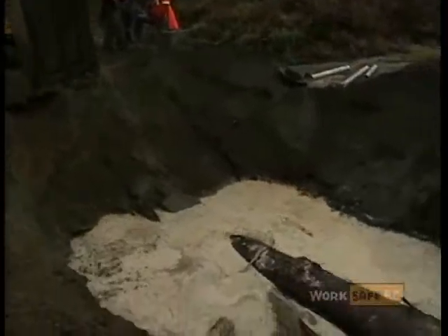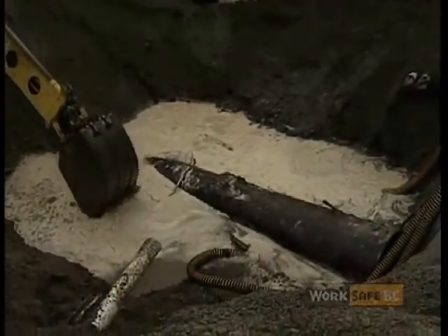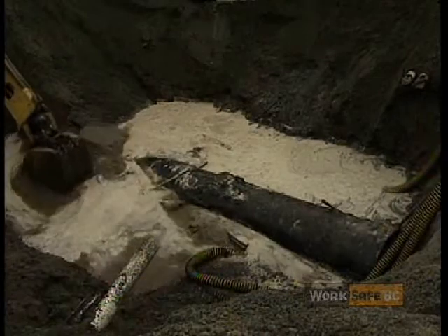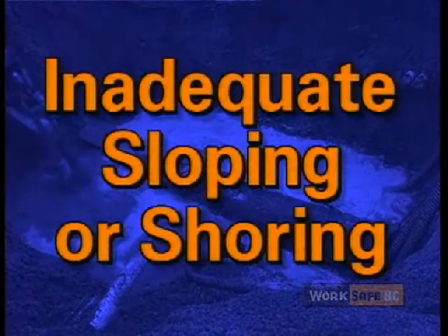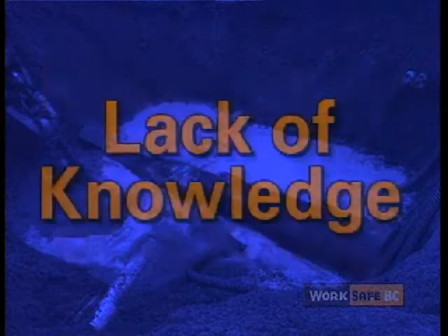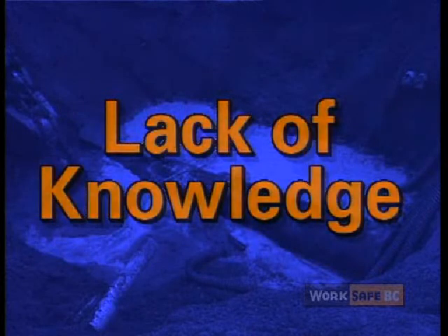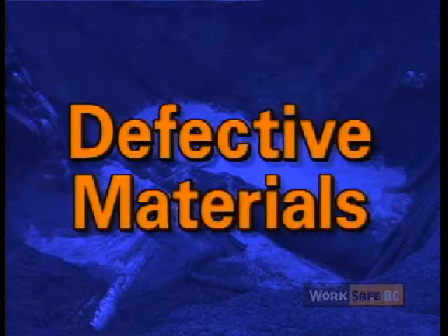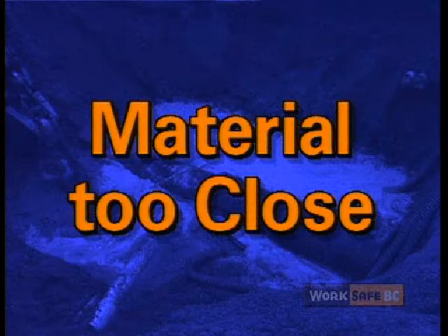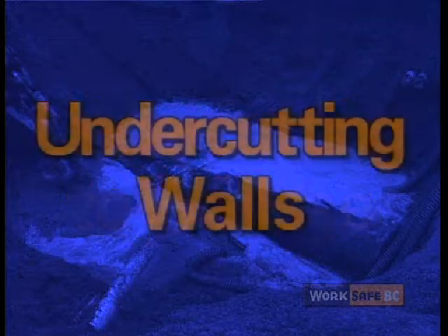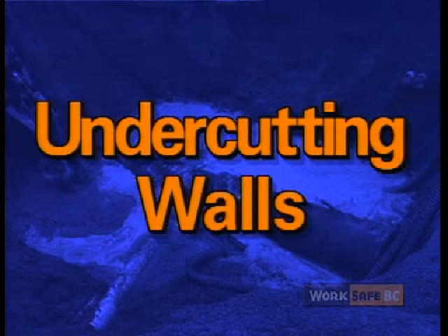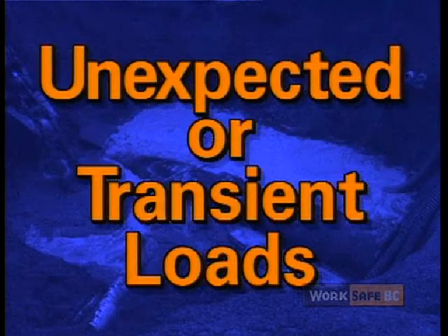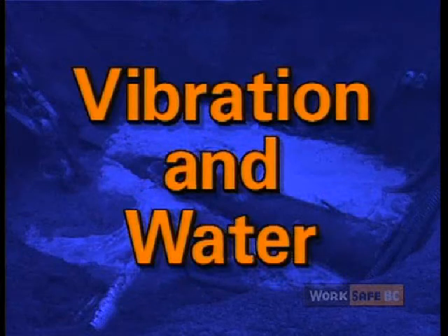Most problems with excavations result from one or a combination of the following reasons: inadequate sloping or shoring, lack of shoring knowledge, poor maintenance of shoring, defective shoring materials, excavated material too close to the edge, undercutting of trench walls, unexpected or transient loads, vibration and water.